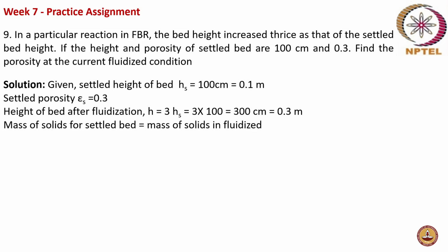So now, in order to find out the bed porosity under the fluidized condition, we have to bring in the relationship that whether it is the settled bed or the fluidized bed, the mass of the solids is not going to change, because whatever mass is kept in is only fluidized. That means the mass of the bed before and after fluidization is going to be equal, right? That is what I've mentioned.